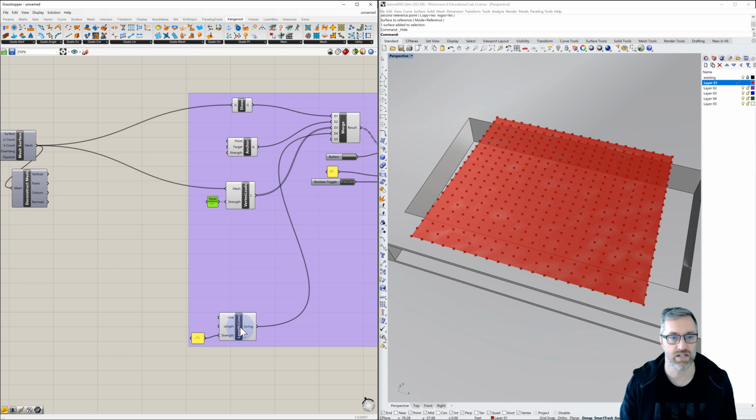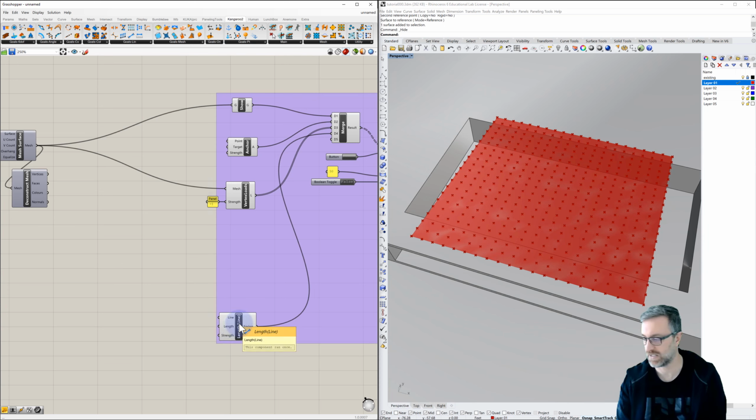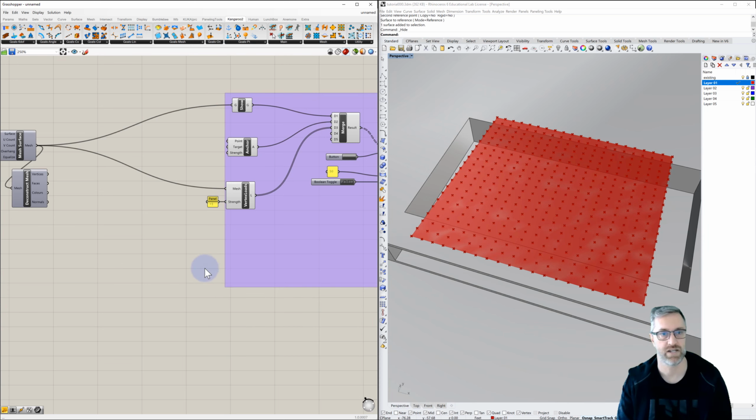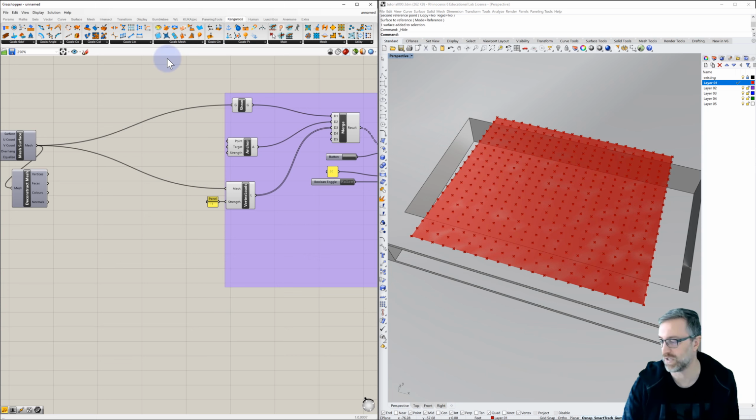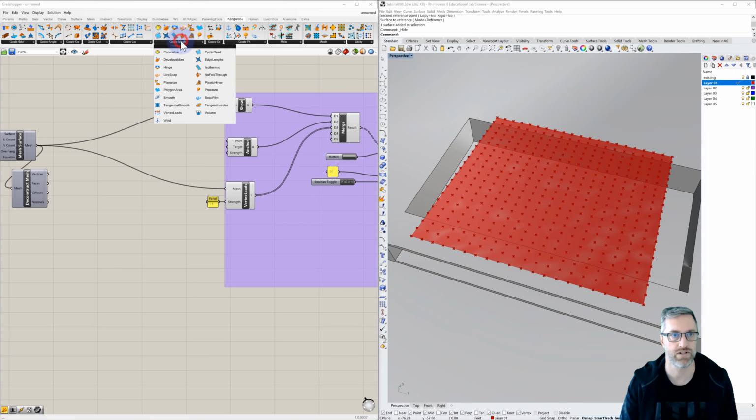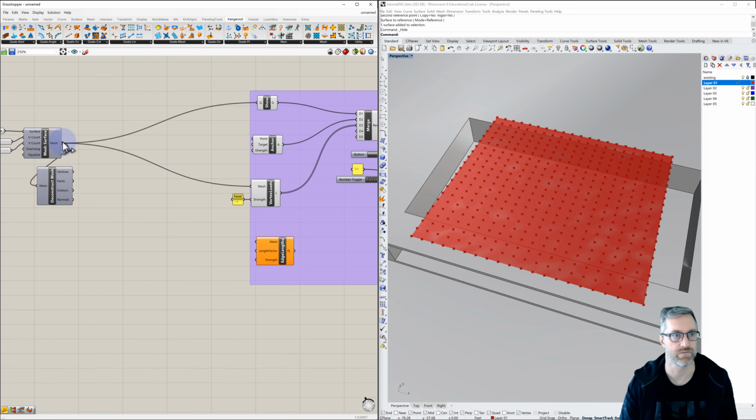The line length, we used this previously. Let's delete the line length, and let's add in a new one, which is also from Goals Mesh in Kangaroo2, that is edge lengths. And as we set edge lengths, we're also going to connect the mesh.